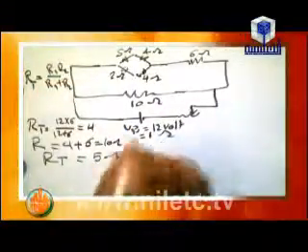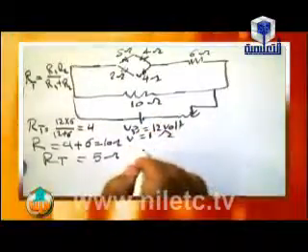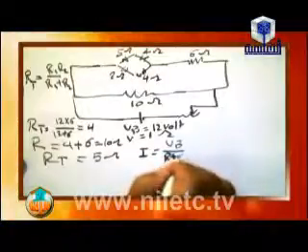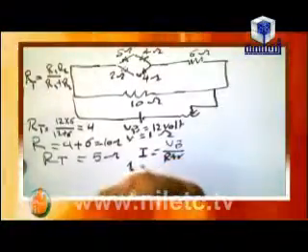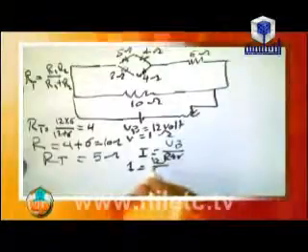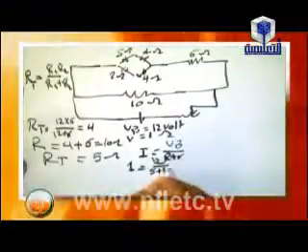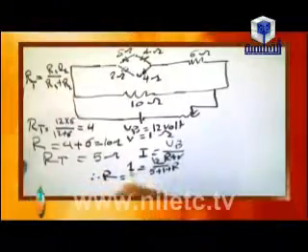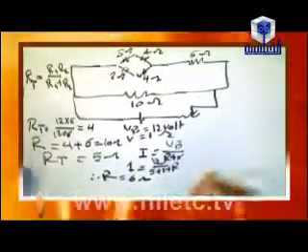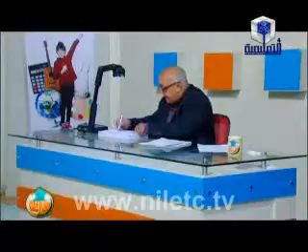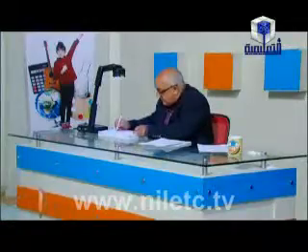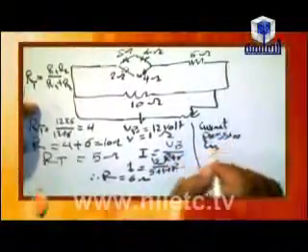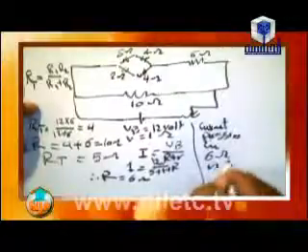So we must find the resistance that must be taken from the rheostat. I equals VB over R plus r. Then 1 ampere equals 12 over 5 plus 1 plus R. Then R equals 6 ohm. Current passing in the 6 ohm is half ampere.